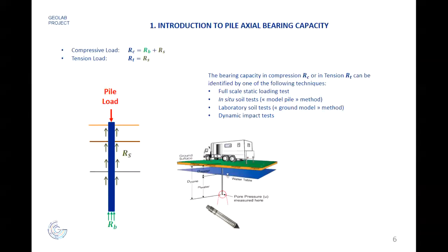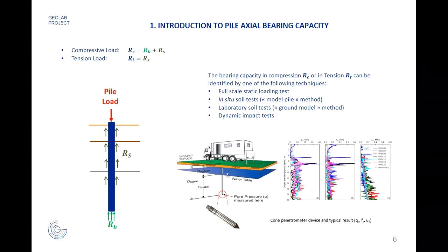It's a small cone with instrumentation, with a force sensor close to the tip. With this cone, we can record some soil parameters like the cone resistance of the soil, which is used for calculating the resistance of the pile following different methodologies.